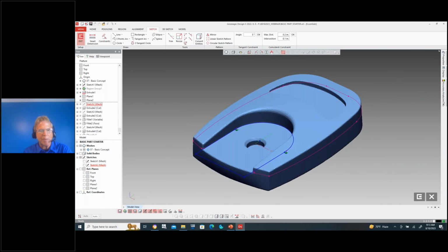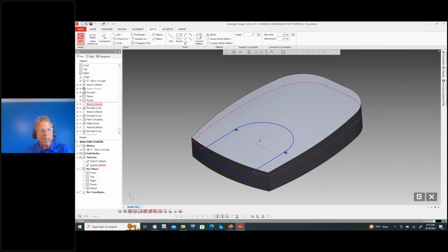So again, going back to the mesh, we can see that the profile is defined at that plane, plane 2, and we have the 2 lines and the arcs, and we have the tangency constraints built in, and we also extended that pocket to go a little bit outside because we're going to cut away that shape. And ultimately, when we pass this into Mastercam, that's the pocket we're going to focus on.